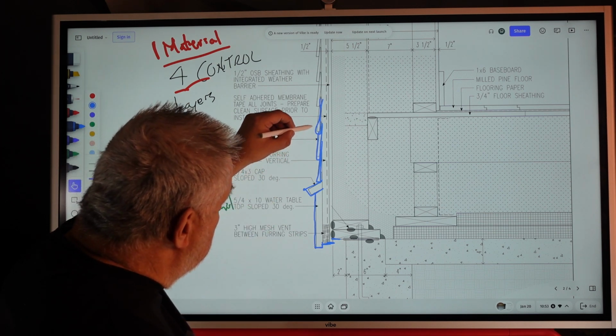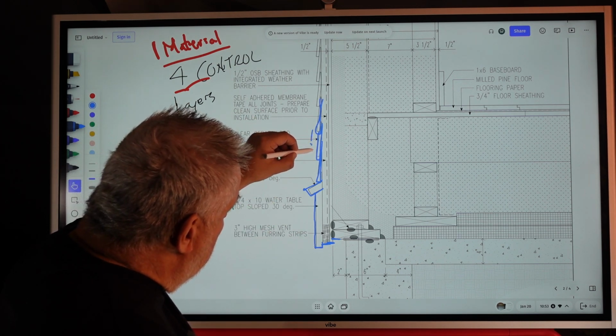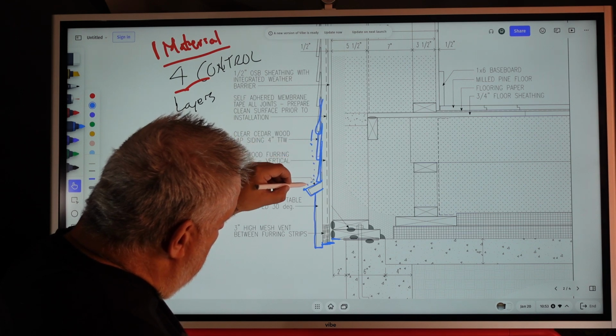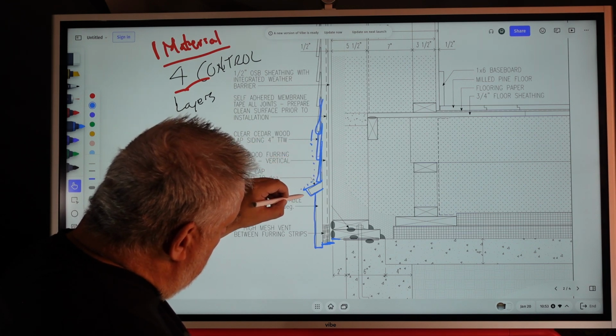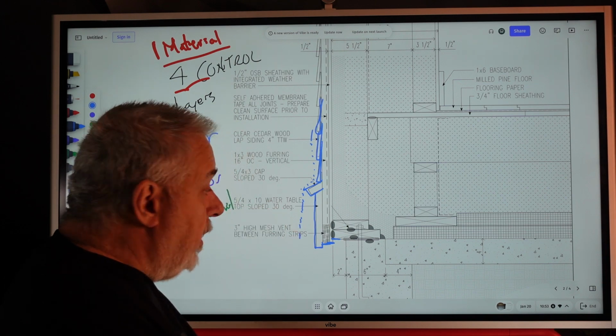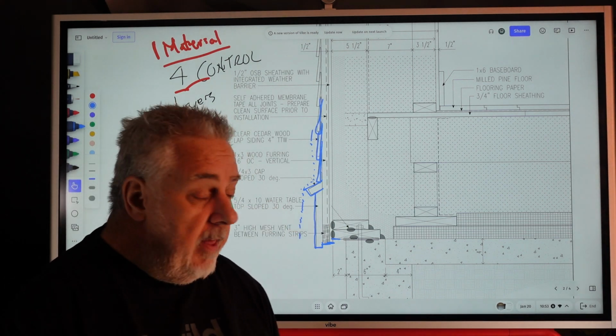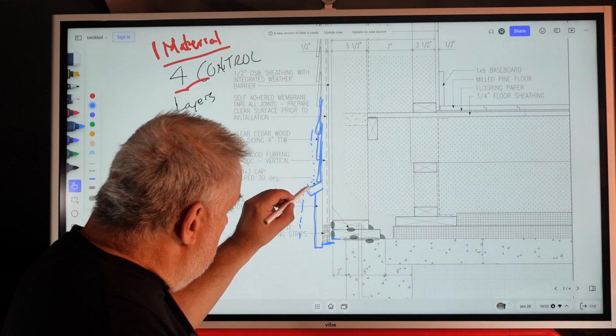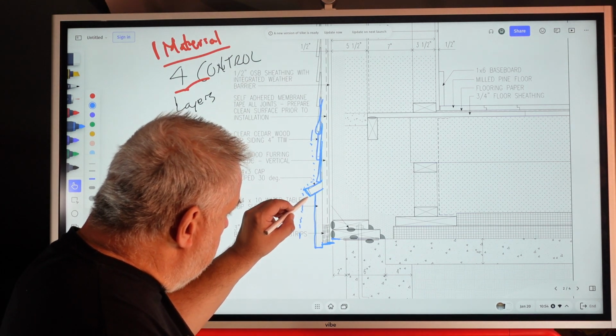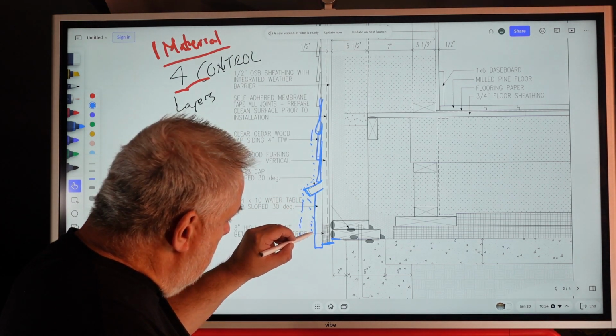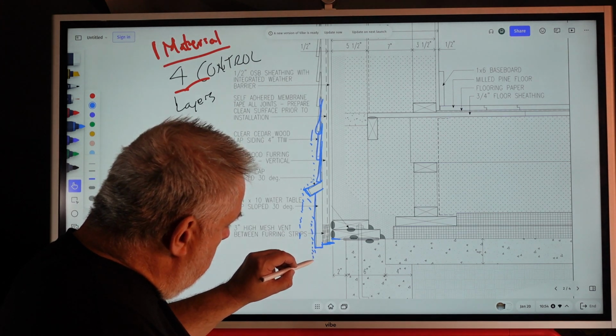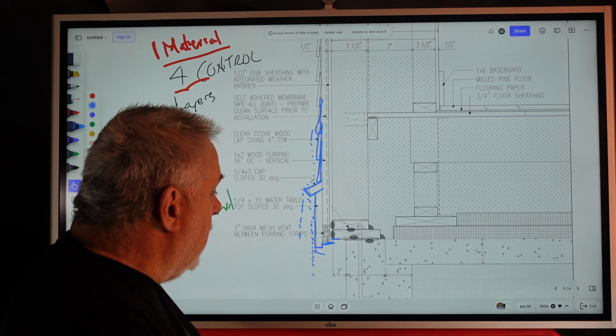The reason is, as water accumulates and comes down here, it's going to go there, and the idea is that we give it the opportunity to drip off the wall there. If for some reason it held here and dripped, or the wind blew it on and it was here, then it would drip here and not turn that corner.